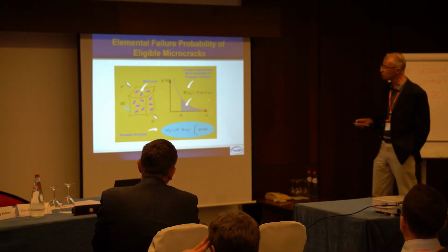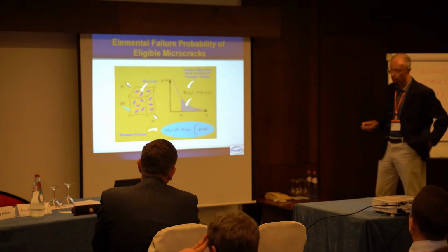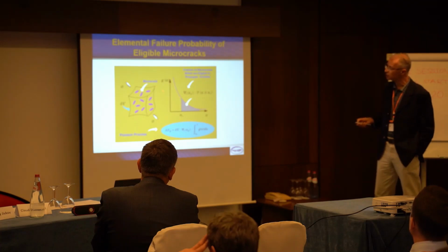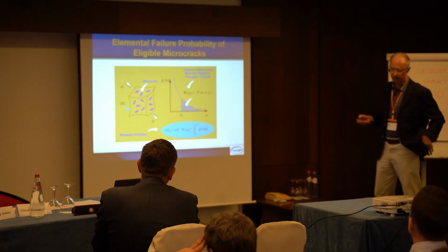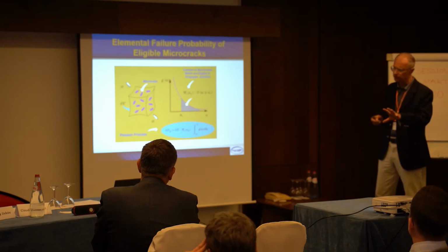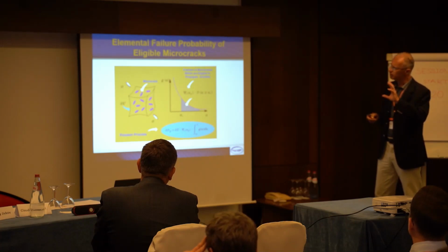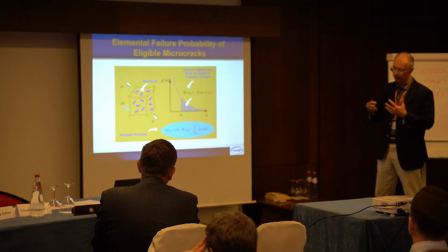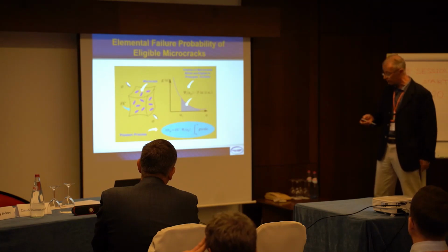So we went back to the Poisson process, to the fundamentals, and then we said, okay, how about assuming that only a fraction of those microcracks, which for ferritic steels are usually carbides at the grain boundary? So many carbides at the grain boundaries under the action of plasticity will break and eventually become a microcrack, but not all of them will actually take part in the cleavage process.